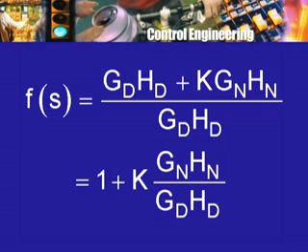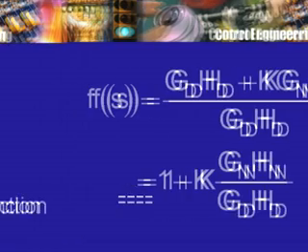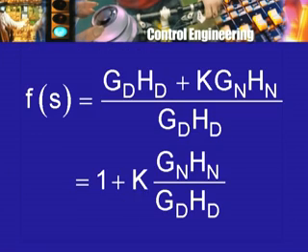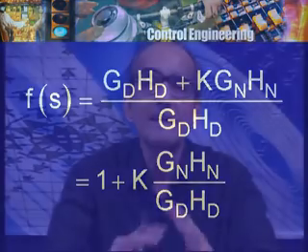Okay. Now, the second thing is this factor k. As I said earlier, in most applications this gain k is a positive real number. So, what is the effect of this k? It multiplies this. It acts only like a positive scale factor, that is, it will just blow up the image by a scale factor. A complex number w is simply going to be multiplied by the real number k.